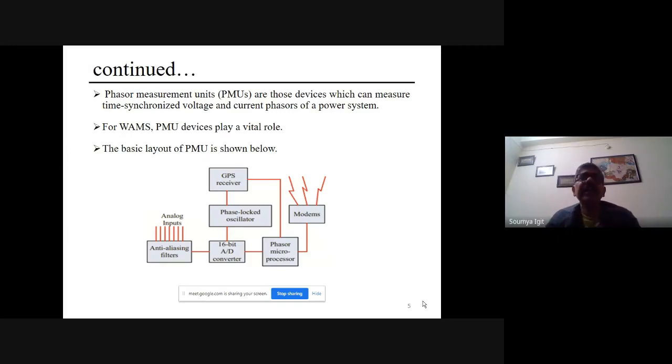You have already taken into account that you have included the same. You have brought in the higher differential equation, subjected to certain constraints, starting from the generation ramp rate, your transmission system thermal limit, and your other constraints, your tie line exchange with the interchange, the scheduled interchange power.